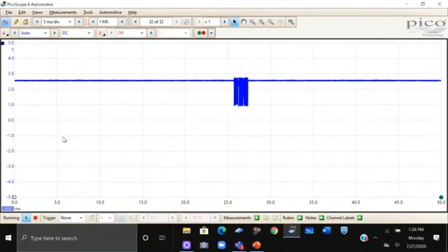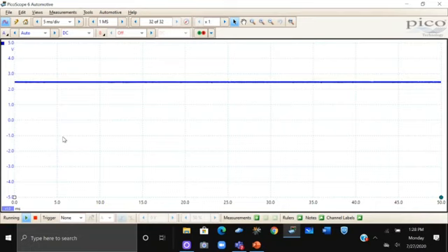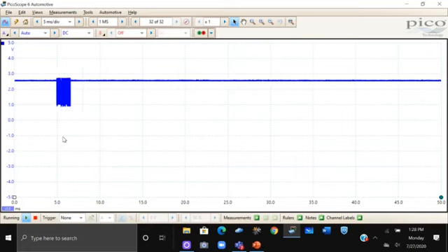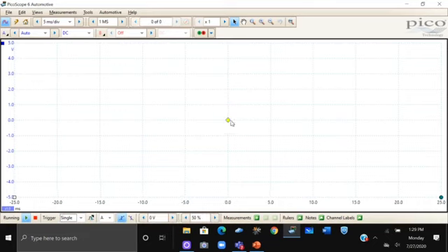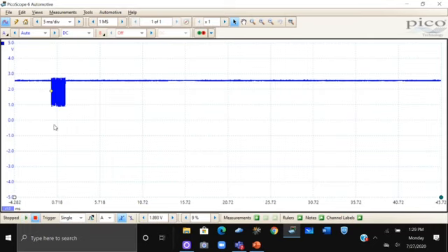The packets are going, and an interesting thing about this, and something that we'll probably have to diagnose, I'm going to turn off my wake-up signal. The system went asleep. Now, as soon as I turn it on, the first blip that goes across, right there, that blip was the wake-up signal. And what you can do with this, from a student standpoint, is say, okay, can we capture this? Yeah, we can take this and bring it up, let's put it about there. Yeah, that'll do it. Okay, now, I'm going to put the system to sleep.